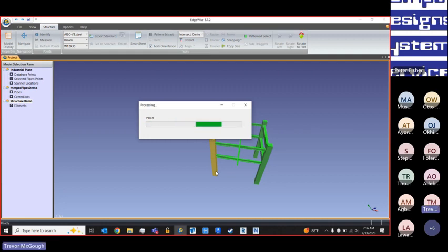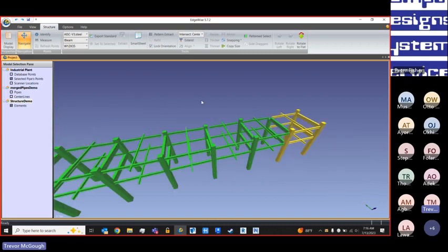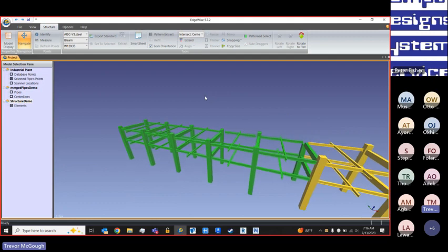In summary, the tool is basically an intelligent array tool. Instead of just doing a blind copy and paste, maybe 10 times every 3 meters, it actually leverages the point cloud data to get true individualized fits for all the different pieces of geometry. There you can see in green, that's the result of the automation with the pattern extract tool.